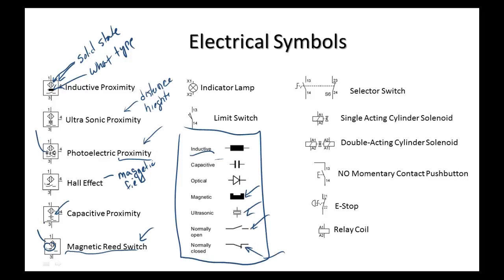I notice it's shown with a normally open. Well, it depends. You can buy them either way. I've never seen a normally closed reed switch. Every reed switch that we've had and played around with is normally open. Seems to me that would be the more logical. Well, it depends on what it does, and we'll see some of these sensors, and you're right, but some of them are normally closed. Some of them actually have a single pole double throw, so you can use the normally open or normally closed or use both.